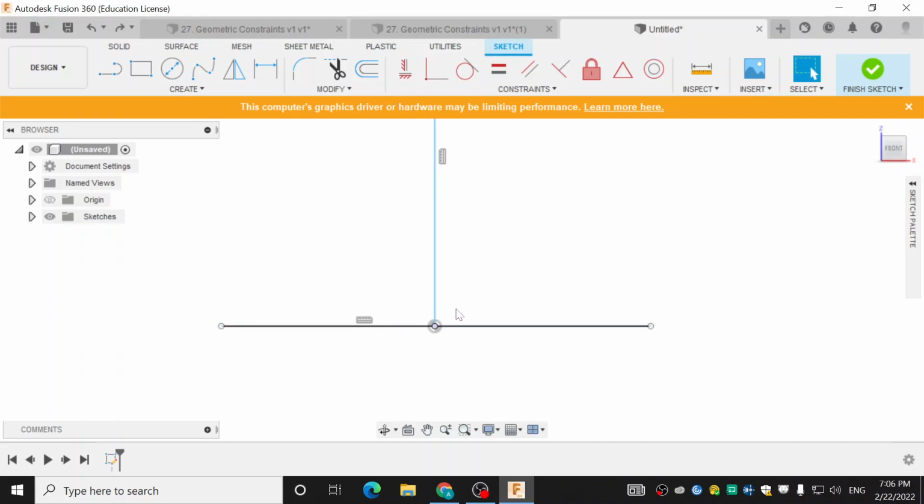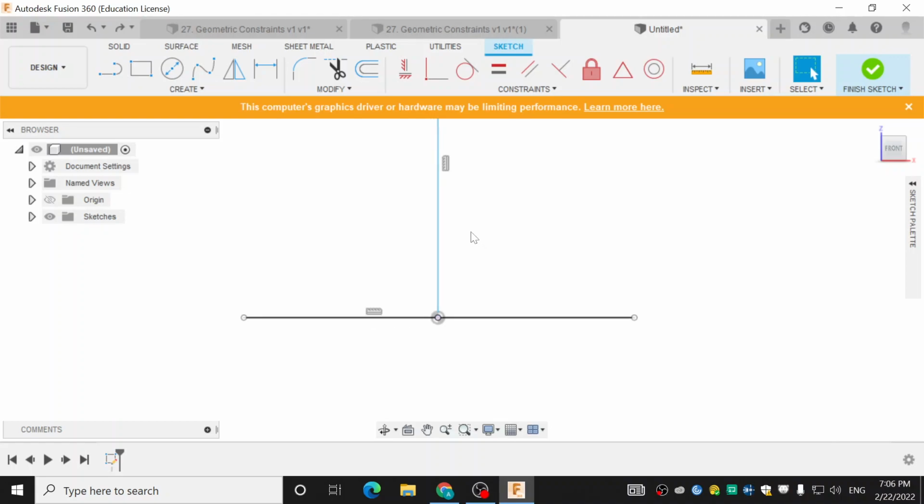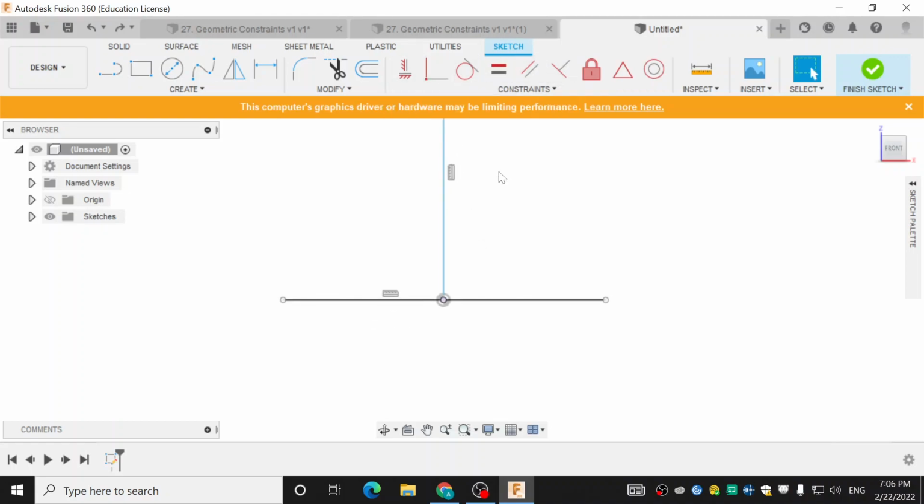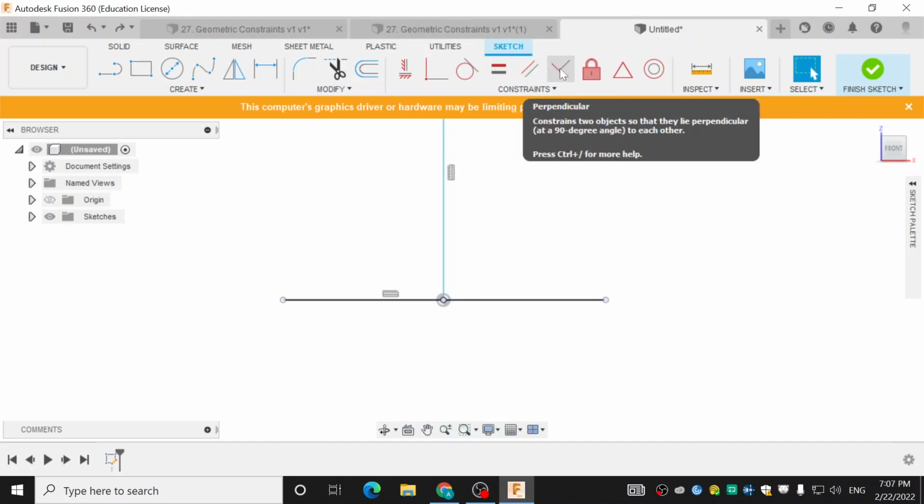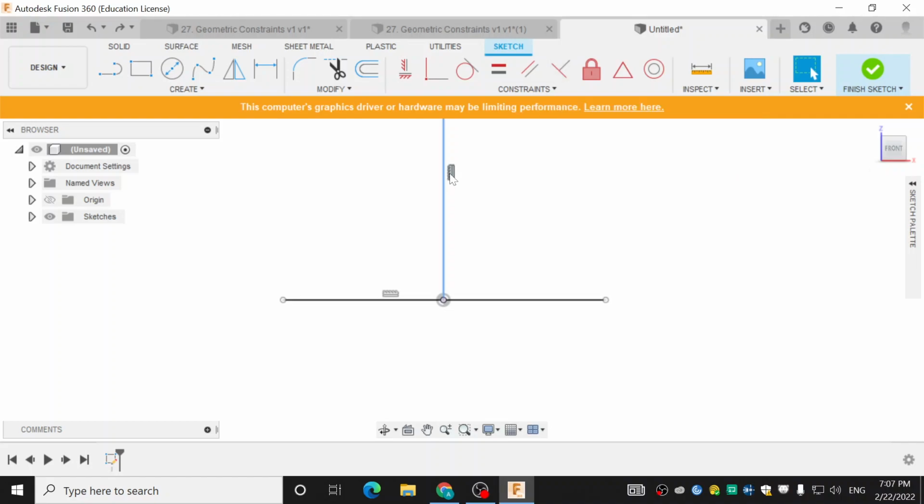Okay. So that one's not popping up, but in this case, if I wanted to delete the coincident, I can click on this one, and there's a simple delete key. If you notice, it turns blue, and then you can move it away. But the reason the perpendicular one is not showing up is because if you notice, this constraint is the vertical constraint, and this one is the horizontal one. So the perpendicular constraint kind of got put into 2 separate things, because, I mean, it's the exact same thing. A perfectly vertical line and a perfectly horizontal line is the same thing as 2 perpendicular. So it deletes that constraint and puts these 2 separately.